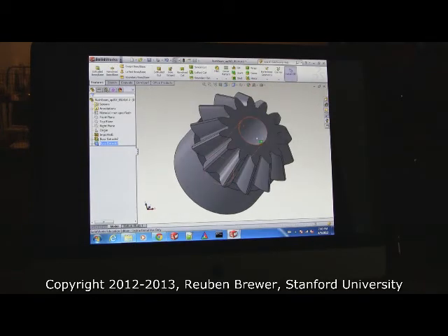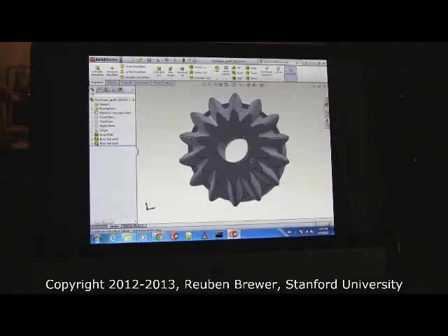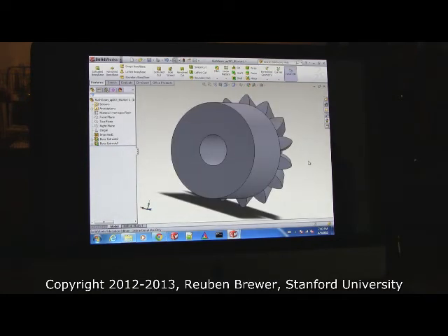So at this point, if we rotate your model, you'll see we have that 8.1 millimeter all the way through. That's cool. That's what we want because we're going to be sticking a shaft all the way through. So it's the sketch is intersecting contours. What does that mean?